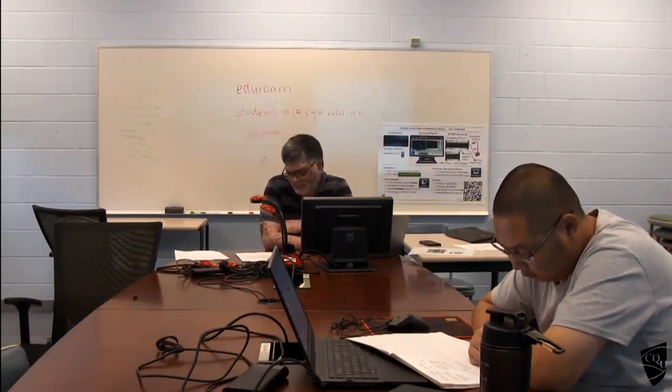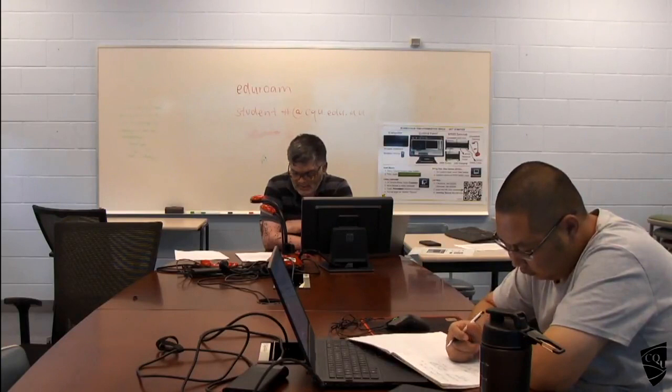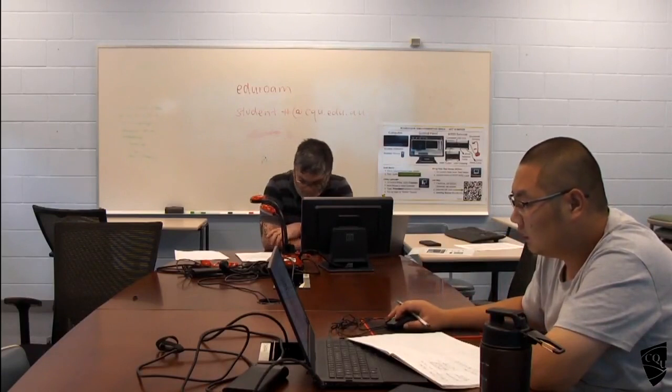You should be able to see the self weight of the tiles and others if you want. If you don't have a project at the moment, you may not have all the details. You may assume superimposed dead loads of 0.9 kilopascal. That should be fine.